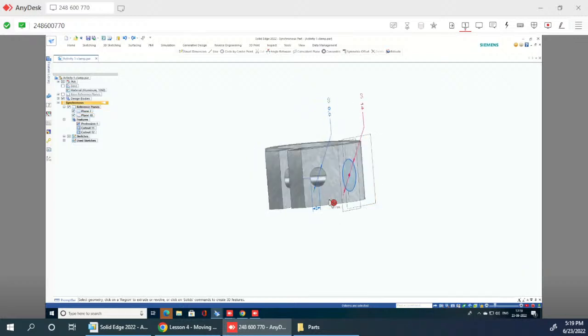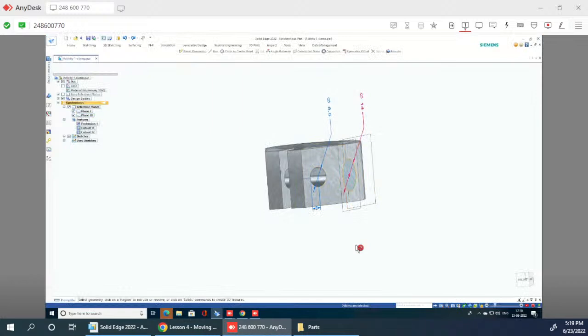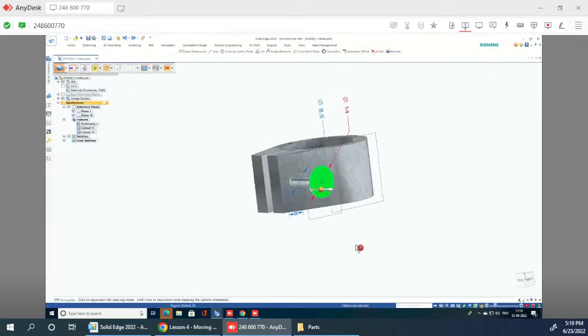So now you have created it on that plane, no? So while extruding this, you have to give that distance which is mentioned in the PPT. Go back to PPT. Okay, so here he is giving the distance now in the middle diagram. So that is the distance you have to extrude, cut. So while extruding, choose negative, not positive. If you choose positive, it will add the material.